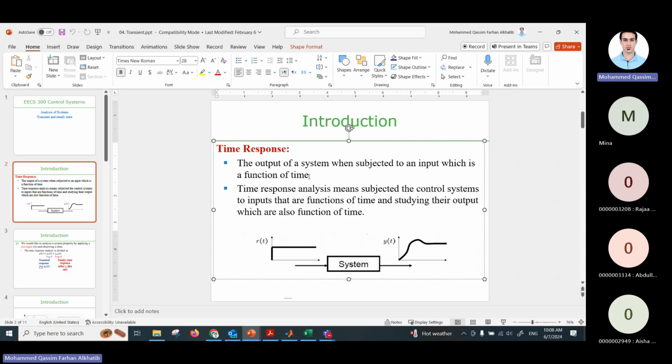However, for us humans, we deal with time. Laplace is another domain to make things easy for us, but as humans, we only deal with time. So usually when you have a system like this, and we apply, this is what we call a step input. So that's an input, a unit step function. And this is what will be the output. So in this case, if the output does not go to infinity, or as time increases, the output increases, in that case, the system is stable as long as it does not go to infinity. If it reaches high values, then the system is unstable.